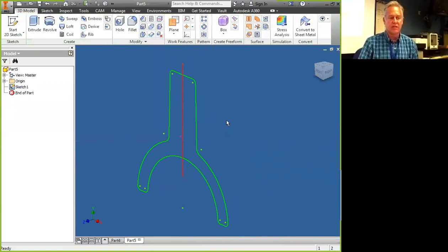My point with this whole lesson is, one, it's an introduction into Inventor without the necessity of sketching in Inventor, and just showing you, as per our objectives here, how to apply constraints and how to extrude and revolve. Those are the first two of four techniques of creating 3D parts rather effectively and straightforwardly. Revolve and extrude are the most commonly used applications of turning a constrained sketch into a 3D part.